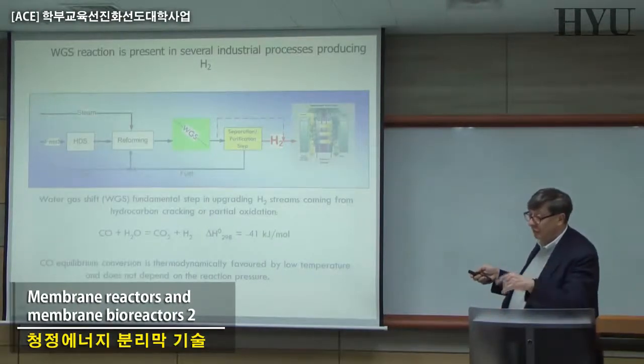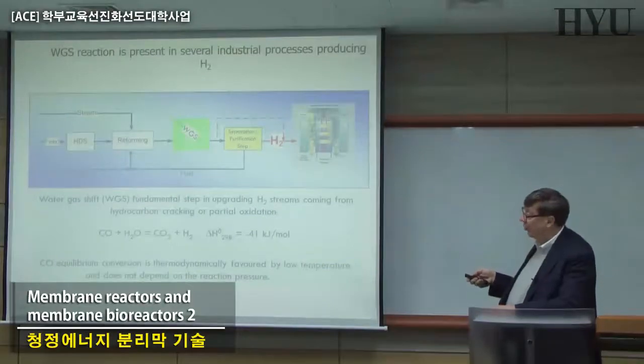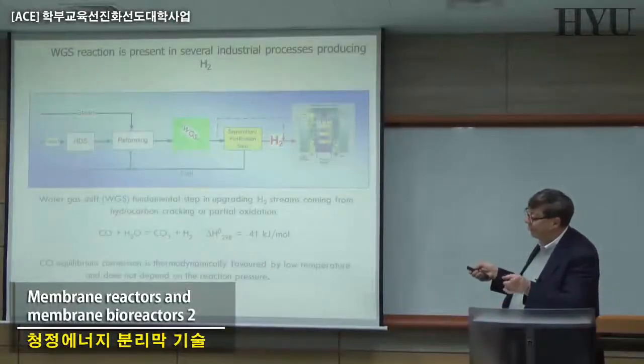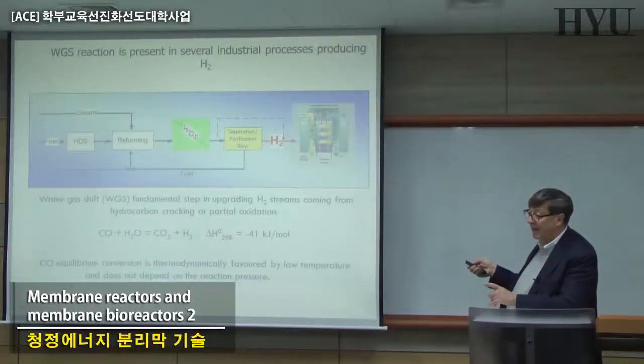After the reaction with methane and water, which is basically here, you can go to the water gas shift, and the CO is going to be converted. Here you have a last step, the final purification with palladium membranes, and you go into the fuel cell.